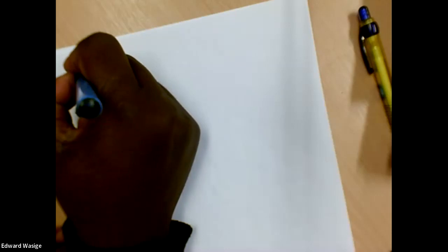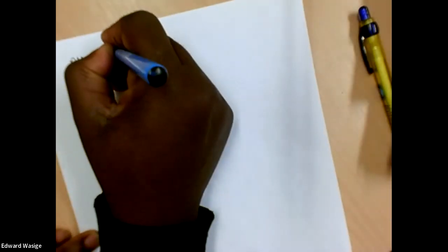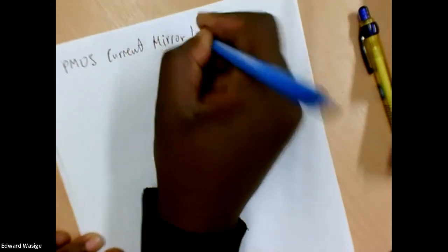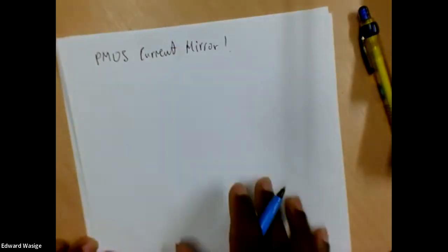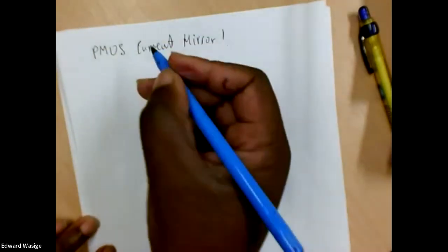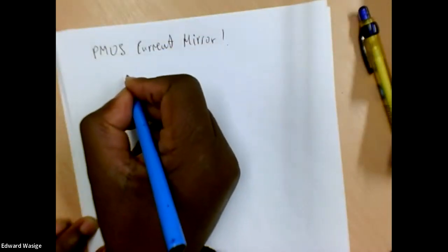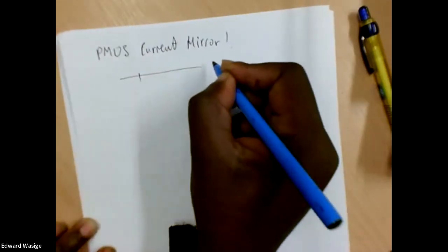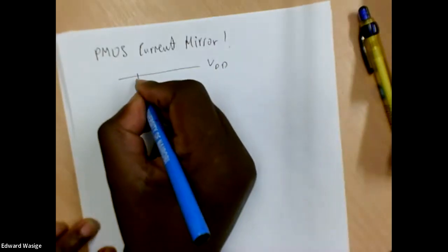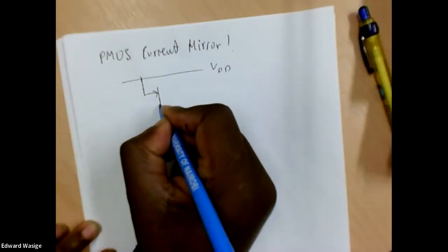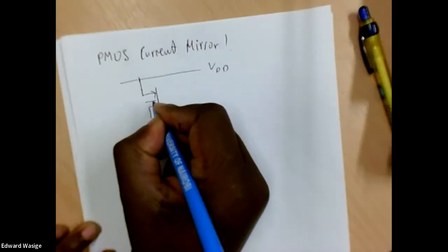So that was an NMOS current mirror, and we can look at a PMOS current mirror. It turns out that the more useful current mirror that we'd like to use, we actually use both NMOS and PMOS. So let's look at how a PMOS current mirror would look. It will also use 2 transistors. Because it's PMOS, the polarity is inverted, and I would draw it like that.